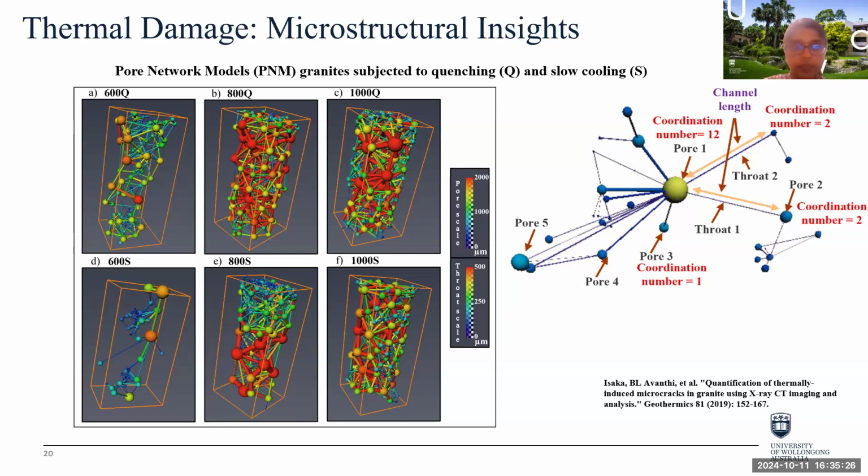of the structure. Finally, we can create a model that represents the interconnected pore and throat spaces using visual elements to show size differences in these components. Pore network models provide detailed information such as pore and throat radii, their coordination numbers, lengths, areas, and volumes, offering insights into structure and function of pore network in fluid and heat transport studies, which I will briefly explain in